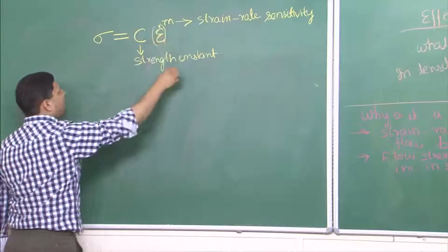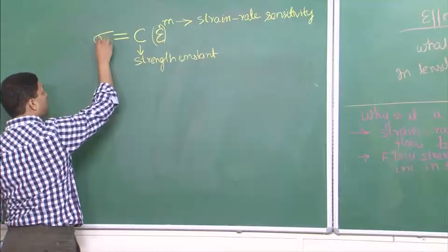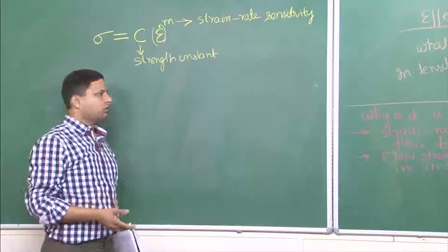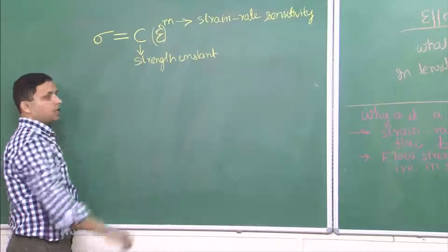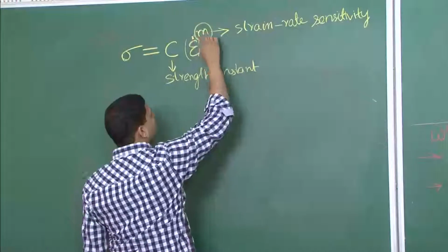This shows how much the strain rate will influence the flow stress. So this is the stress required for flow behavior, meaning you can again say this is the yield stress of the material after a given deformation. So how much different flow stress is required for a given amount of strain will depend on this value M.